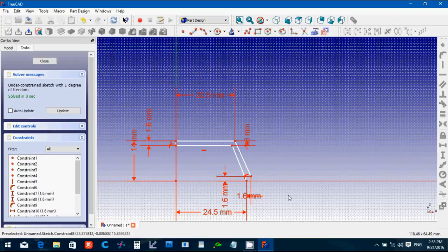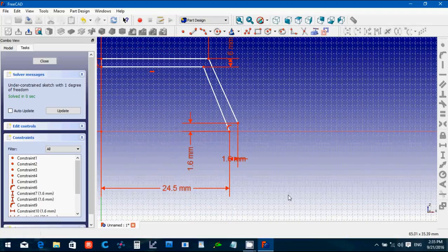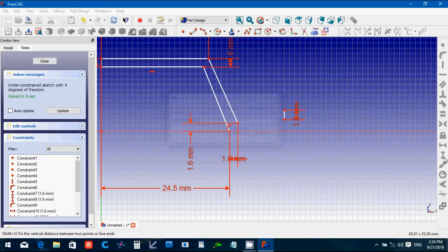Okay. Now the tricky part is how this curves up slightly. So we're going to need, I'm going to make a small line out here. I'm going to set that one to the 1 point. I'm going to go a little bigger. I'm going to go 1.8. And then I need it to be 70.2 diameter, so 35.1 millimeters away from the center.